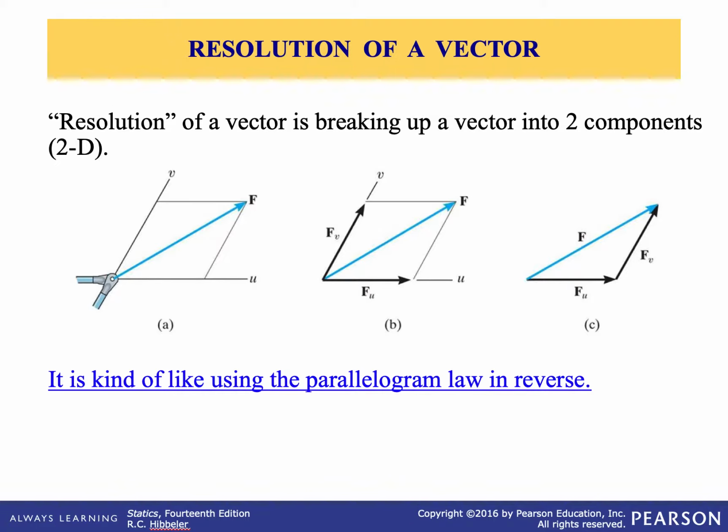We are still talking in lecture 2 about force vectors. We provided a quick summary about the difference between vectors and scalars, and we talked about multiplication of vectors with a scalar and then addition of vectors. Now we want to go a little bit more into vector analysis and talk about resolution of vectors. Two common problems in statics involve either finding the resultant force, assuming that we know the components, and the second one is resolving a known force into two components, just reversing the first process.